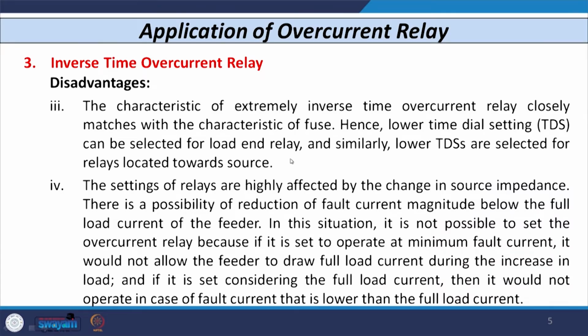So, that is the third disadvantage of inverse time overcurrent relay, and we can also resolve this issue if I use the extremely inverse overcurrent relay. Let us further proceed. The fourth disadvantage of this inverse time overcurrent relay is that the settings of these inverse time overcurrent relays are highly affected by varying generating conditions.